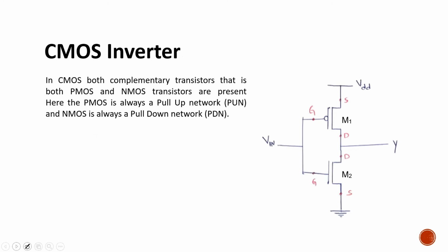Yes, this is a CMOS inverter, guys, where in place of the RL resistor, we have used one PMOS. The PMOS transistors have different symbols: in analog with arrow marks, in digital with bubbles. Remember, guys, whenever you have a bubble, it is a PMOS.